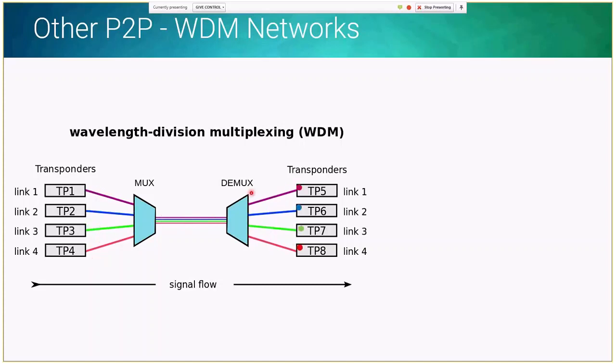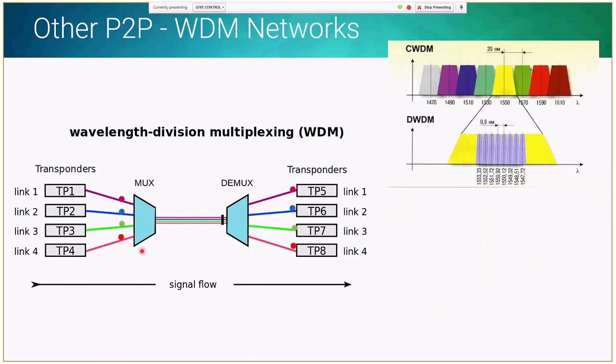These elements can be passive as well, and it will feed back to the receive side of the transponder, the communication. And this also means that if you would have the second segment where the B side transmits to the A side, you would need to use a separate fiber. So one fiber for the uplink and one fiber for the downlink. Why is this so important?